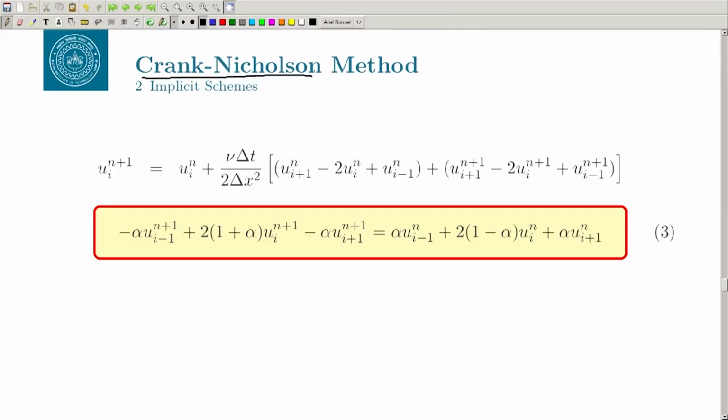So, as we have been discussing, the jump should not be more than basically the grid cell size, okay. And that is what limits your delta t, the time step, right. We will see shortly that when you use the implicit scheme, that means your right hand side is also available at n plus 1 while calculating, then the restriction on delta t goes away. Okay. So, you can use a higher delta t. That is a very big thing in CFD.